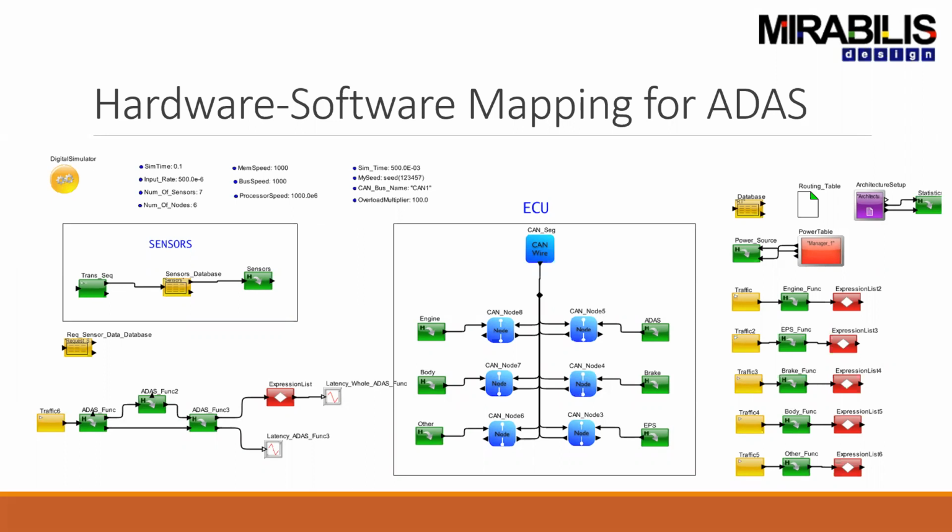Earlier on, if you look at the old way of doing things, we'd say, oh yeah, let me put my sensor on this network, my ECU on this network, and I only care about the data movement between the sensor and the ECU. But now you have ECU to ECU type traffic, which is going to cause a lot of system bottlenecks. So your allocation is not just limited to worrying about sensor to ECU and ECU back to actuator, but rather it can be incremental traffic as well.